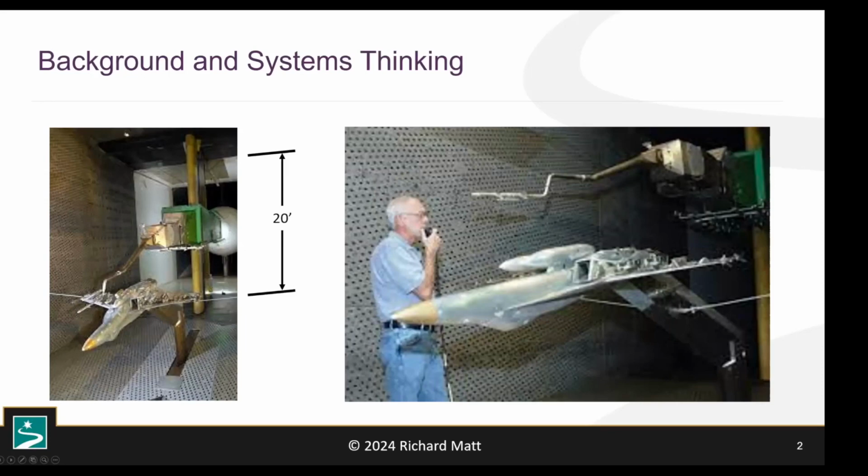These are pictures of the AEDC's transonic wind tunnel with its 20-foot by 40-foot long test section that consumes over 250,000 horsepower when running flat out. Those dots in the walls are holes, and a slight suction would pull on the outside of the wall to suck the air's boundary layer through the holes so the flight vehicle appeared more closely to match its flight characteristics in free air. It was an amazing place to work.